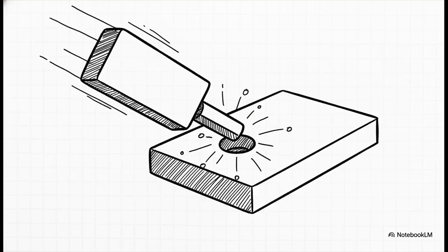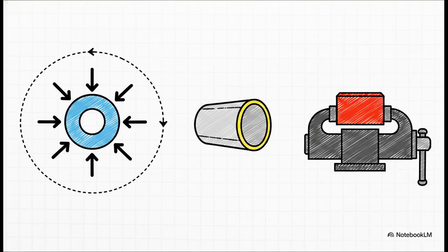By combining dimensional and geometric tolerances at MMC, we create this maximum envelope known as the virtual condition. And this is awesome because it allows production lines to use hard go gauges. A go gauge physically simulates that worst-case mating boundary, so inspectors can literally do lightning-fast, pass-or-fail physical checks right there on the assembly line without having to rely on complex CMM programming. If the gauge goes in, the part is good. Simple as that.